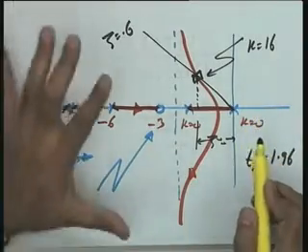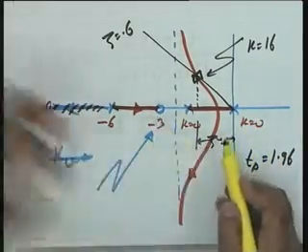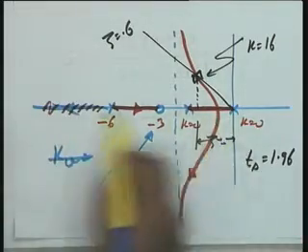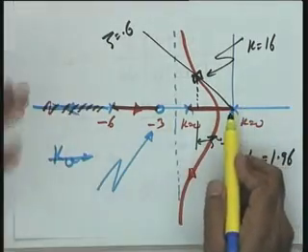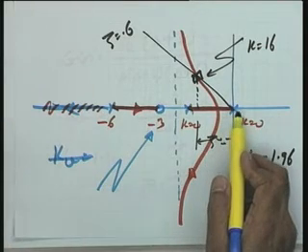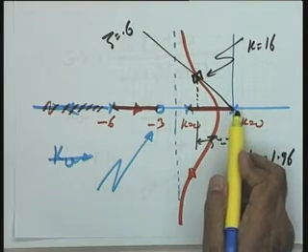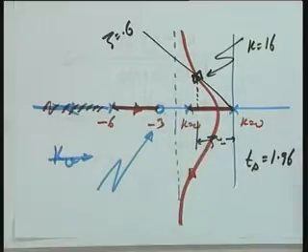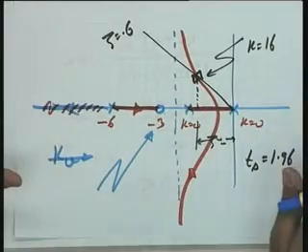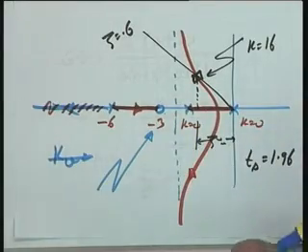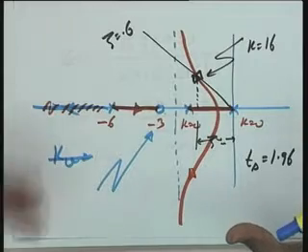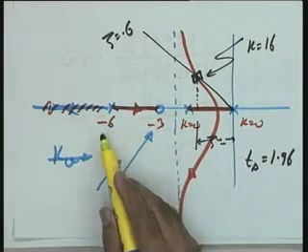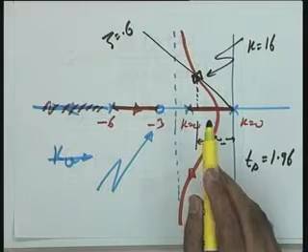We have seen that adding a 0 has a potential of changing the design, and by trial and error adjustment here and there, it is now possible to meet the requirements on zeta, settling time, and the Kv by placing the 0 appropriately. And once you have got this idea, the CAD software becomes very useful, because the trial and error become quicker there, whether it has to go this way or that way, it depends.